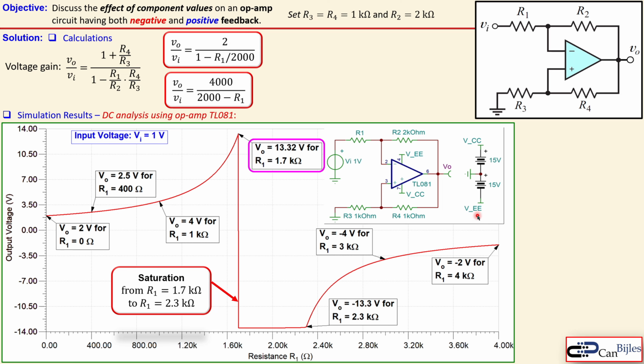Because the operational amplifier is also powered by a finite power supply, which is the 15 and minus 15 volts. So you might say, why don't we see this 15 volts also here? Because the operational amplifier will also consume some power. That means we don't get the full 15 volts at the output. So you will lose approximately 1.5, sometimes 2 volts for each direction of the power supply.